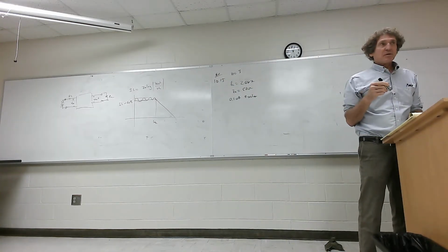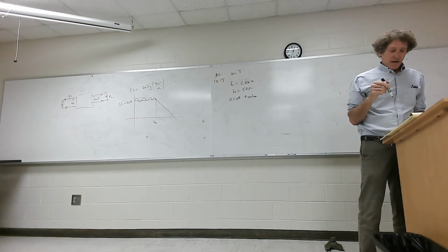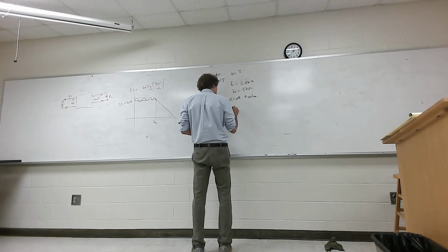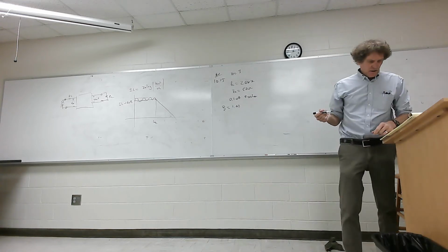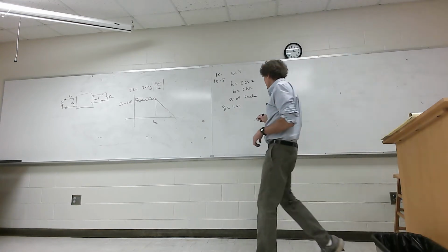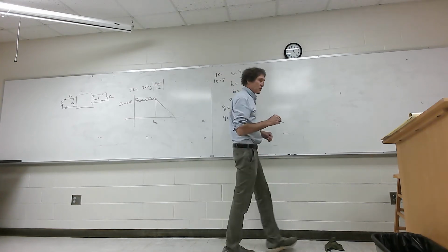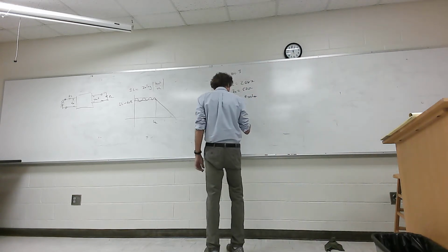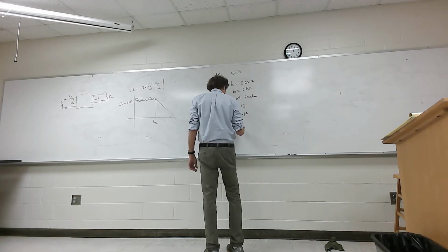You look in the table, you'll have your books here. If you look in the table, just look where it says 0.1 dB ripple. If you go down there, you're going to see G1 is equal to 1.0315, G2 is equal to 1.1474, and G3 will be equal to G1.